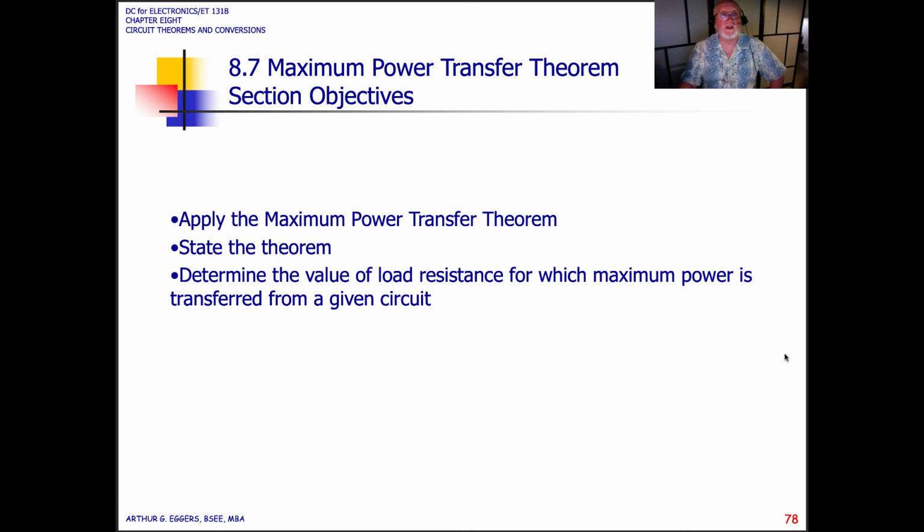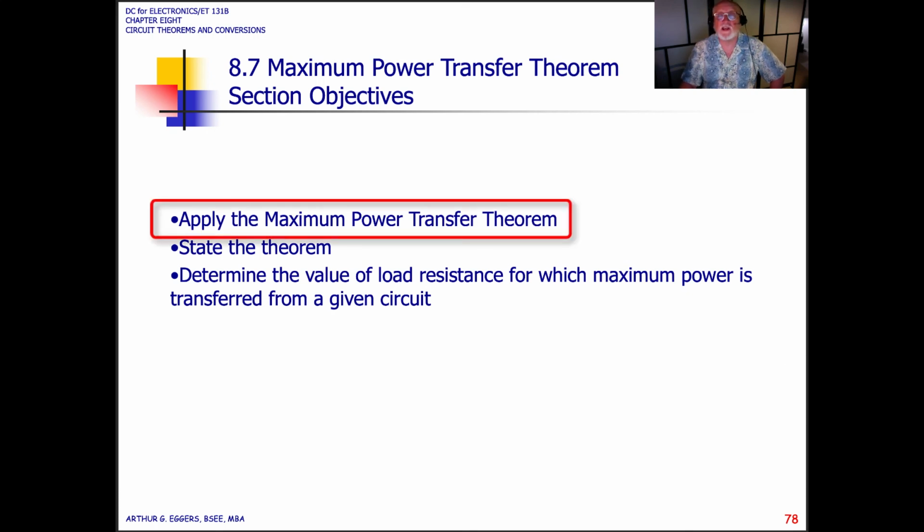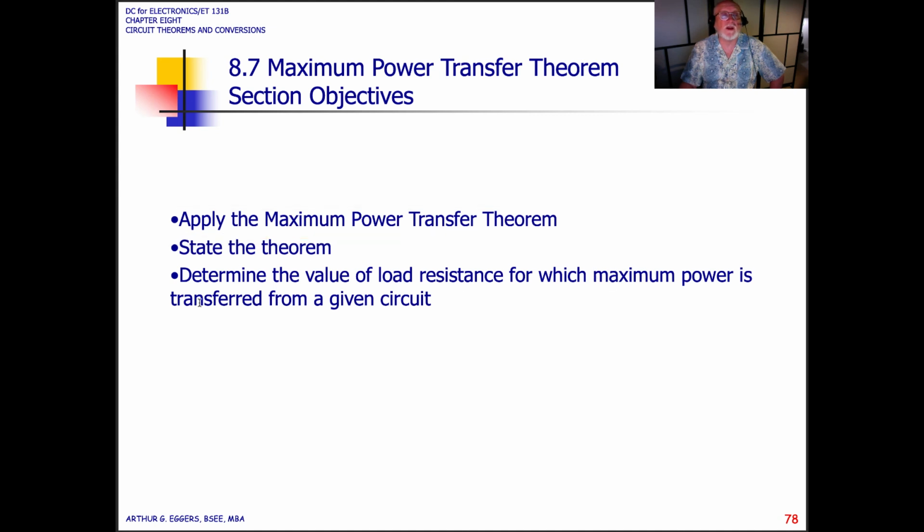In the next section, we're going to look at something called the maximum power transfer theorem. In this case, we want to make sure that we have our load matched properly and that we get the maximum power on the output. This is very important for things like audio systems where you want all of the power delivered to the speakers so that you're not losing anything or overdriving and getting distortion.